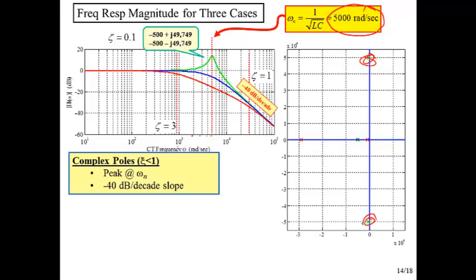Notice how close the poles are to the j omega axis. So this is the j omega axis. Shame on me, I didn't label my plot. This is the sigma axis. We can then see that when the poles are close to the j omega axis, we get this spike, this peak, and that's called a resonant peak. Not resident, resonant. But some other things we can see is that down in our low frequency passband, it's nice and flat at 0 dB.